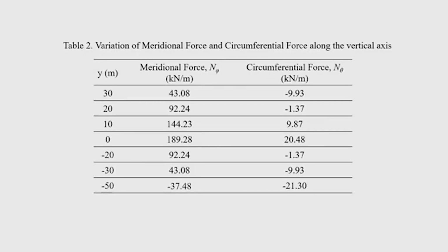Now, choosing a diameter of the steel bar, generally in thin structure, here the thickness is 150 mm, maximum you can provide bar diameter from 8 mm to 12 mm within this. So, you can see the spacing of the reinforcement will also not be very large, and the requirement of reinforcement will be less.